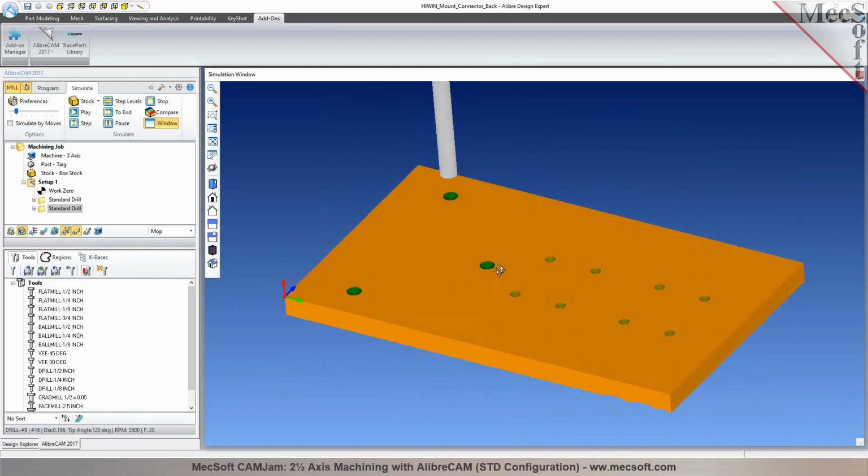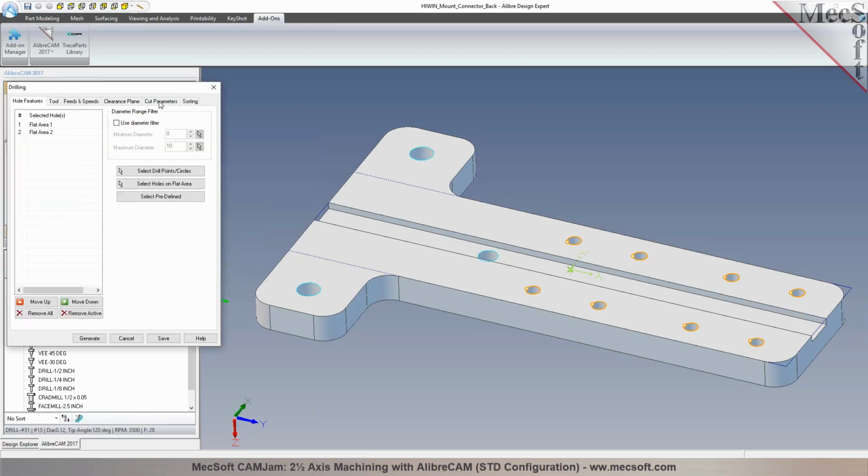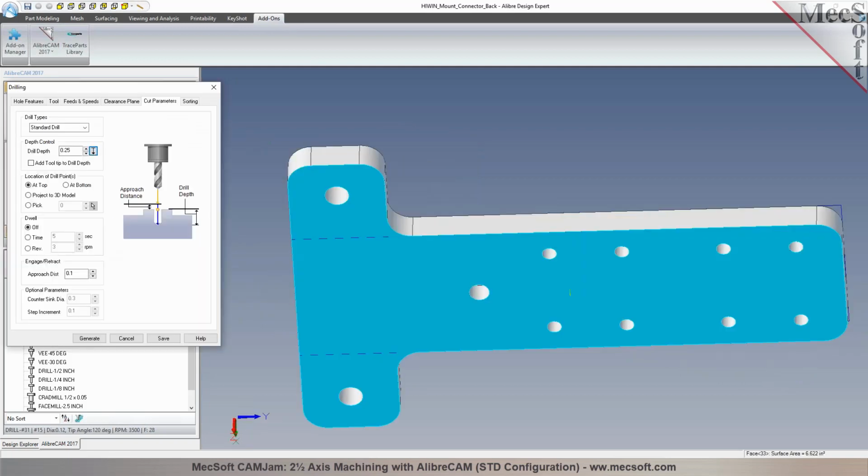All right. Okay, so now next step is basically you want to drill all the way through, right? Yes. Okay, so I can repeat the same operation in here, copy and paste it, and we have the drill number 31 in here. Now I could have done this to minimize tool changes. First I can call this spot drill. And then I could do a deep or through drill in here, and I can specify the depth by just picking the top face. I can go pick the bottom face.